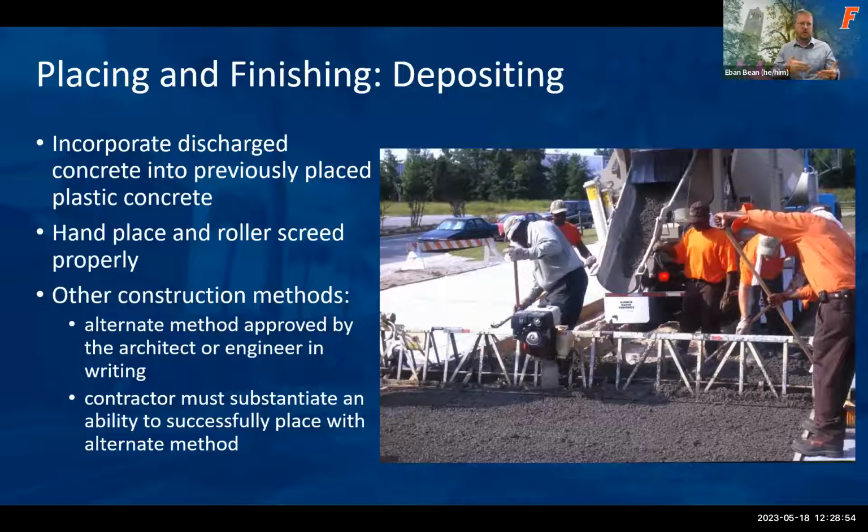When we're putting it in, you want to screed it, basically hand placing it and then roller screeding it so that it is even, basically running across the top of your forms. There are some other ways that it can be installed, but be sure that that is approved by the architect or the engineer who's doing it.